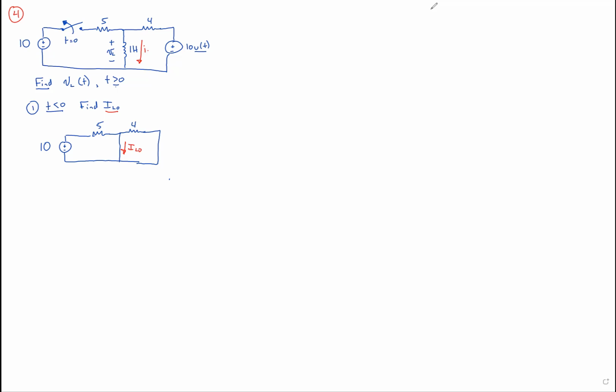It's kind of an odd looking thing, isn't it? I think if I was to redraw this, maybe you guys can see it already, but it might be more helpful to redraw this. All I did was move that 4 around on the side. And I hope it's clear from the way that I drew it that this is like a 0 ohm resistor in parallel with a 4 ohm resistor. So that would have a total impedance of 0 ohms.